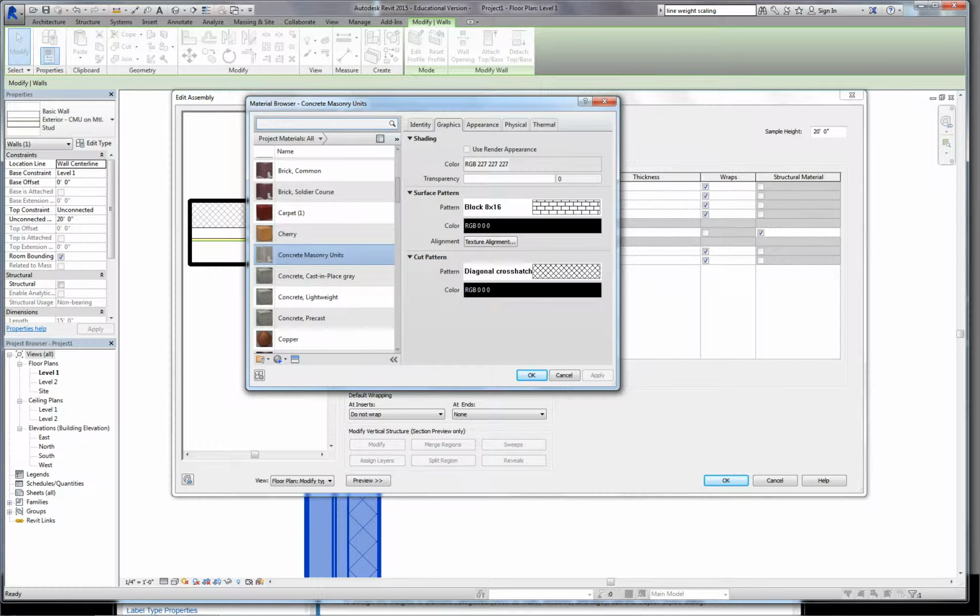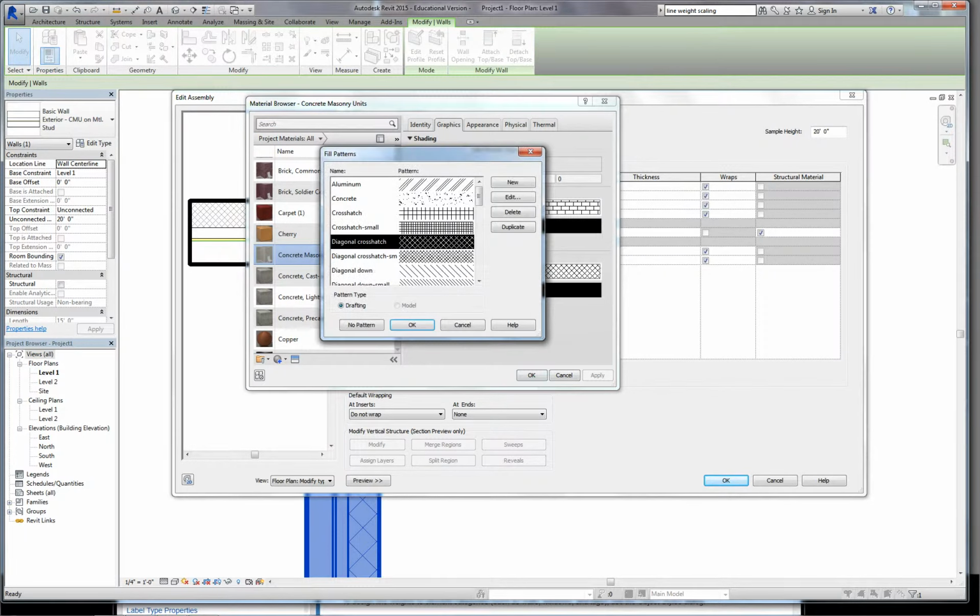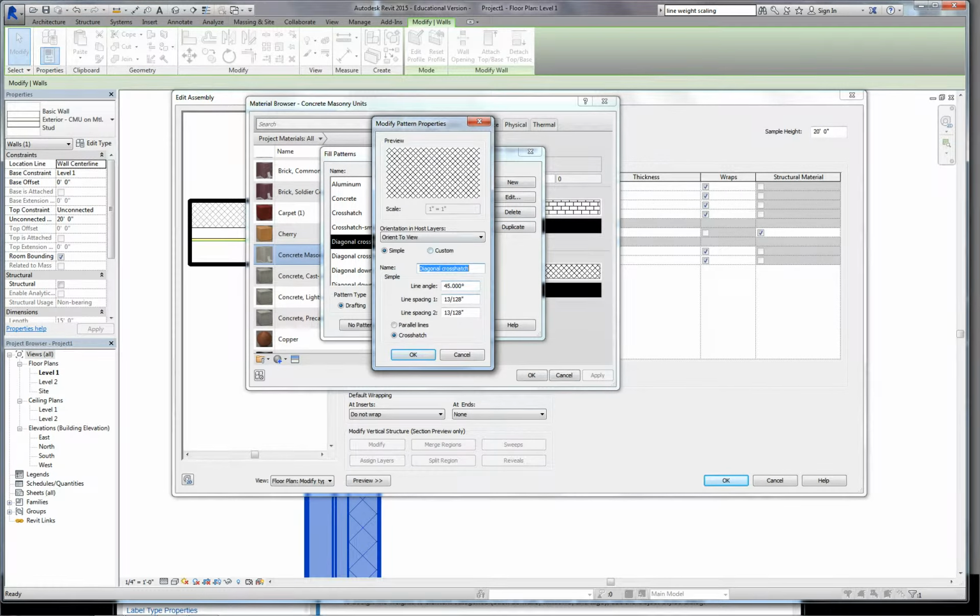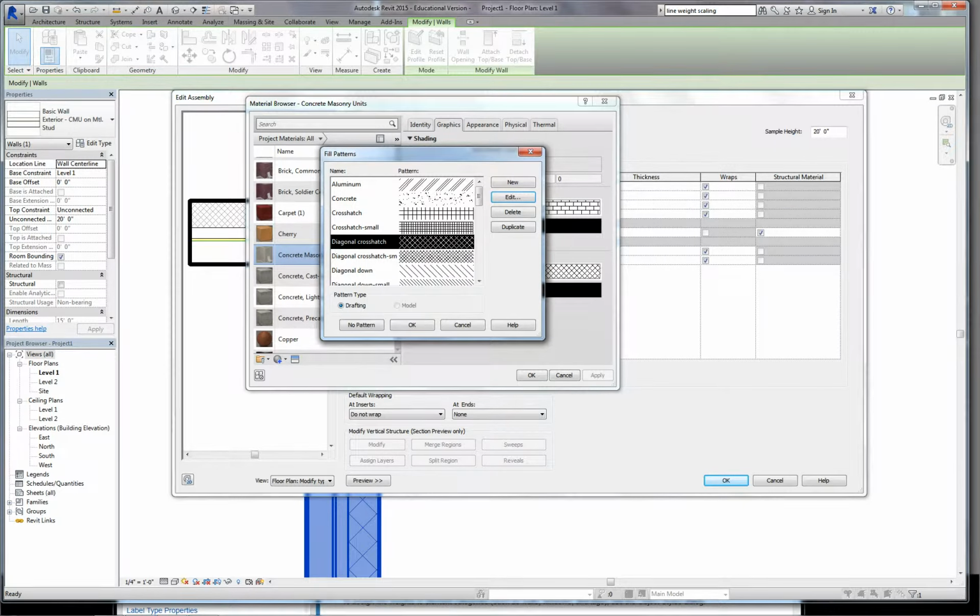This is really important, especially if you're doing floor plans and we don't like what the floor is looking like for wood finish. We can adjust that or turn it off, give it a color. We can come here and adjust the pattern and change the spacing, based on what we want to do, or change the angle. So you can customize these. Typically they're set up properly, right? But if you want to customize them, we know how to.